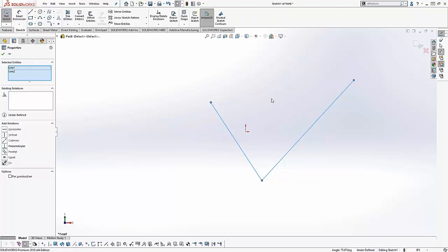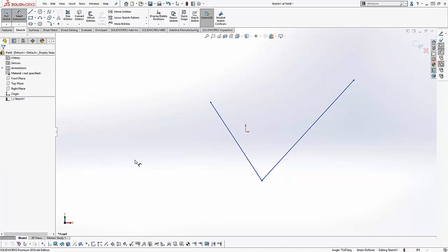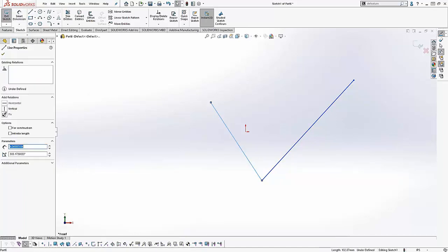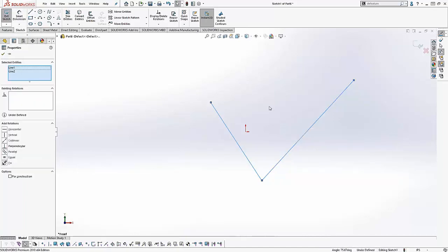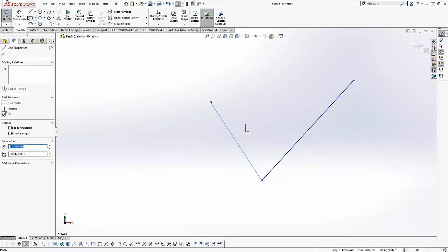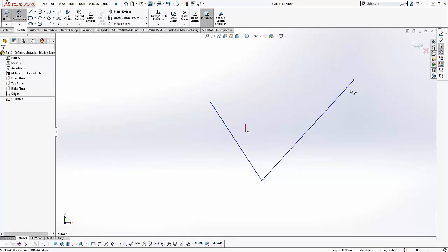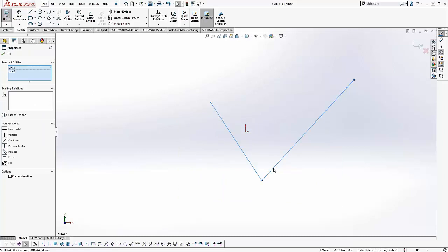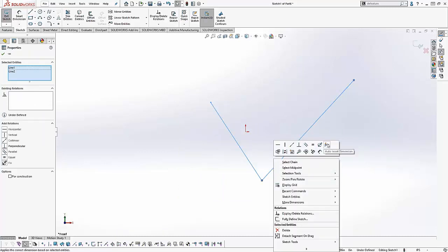That would actually generate a dimension, an angular dimension between the two components. Now you'll see that that's actually been removed. If I try and use the Smart Dimension tool for that, pre-selections are no longer respected. The reason we did this is a number of instances we would pre-select a component before accessing the Smart Dimension tool and then try and dimension a second component and cause a lot of problems within the software. So instead this year, to perform the same interactions, the same behavior, pre-selecting models, if you select them and get the heads-up toolbar, you'll notice there's a new option called Auto Insert Dimension.